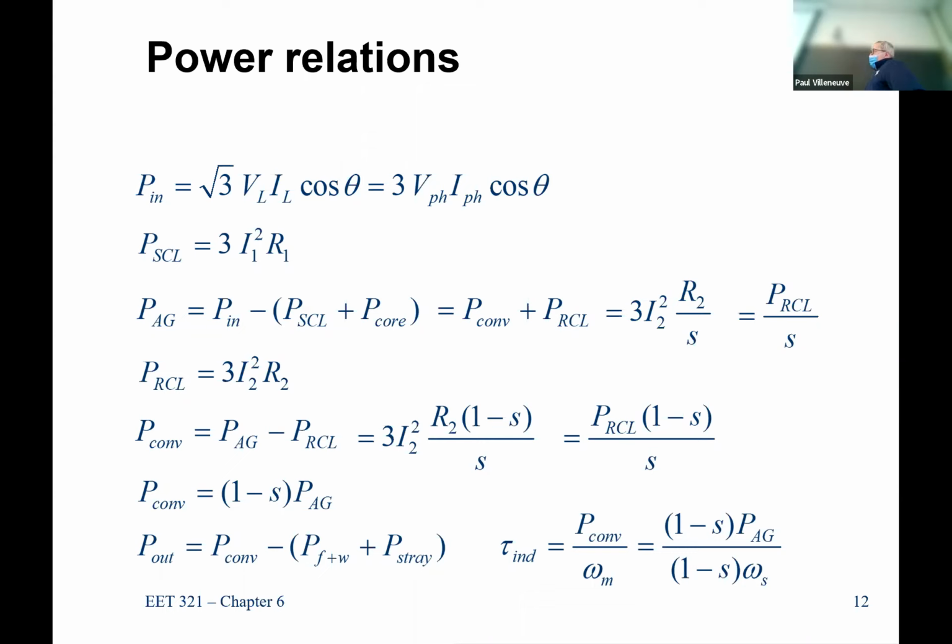I did have one application when I worked at a nuclear plant. They had wound some motors that kept burning out. These were compressor motors, and they just kept rewinding them with higher class insulation, thinking they could handle the higher temperatures, but they kept burning up. Well, the reason why they kept burning up is the core losses. So they were pushing them harder, which means they were moving more magnetic energy through, which means they were getting more eddy currents. And so they just kept burning up the cores until finally they scrapped them and ended up replacing them with much better quality, bigger motors.